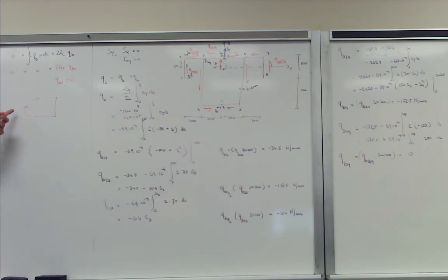And thinking ahead, in the previous example we knew that if we have the shear flow, we want to take the moment around it, so the moment arm would always be equal to R in this case. So you can always think a bit ahead to see where it's convenient, but starting off at a symmetry plane is always the best thing to do.